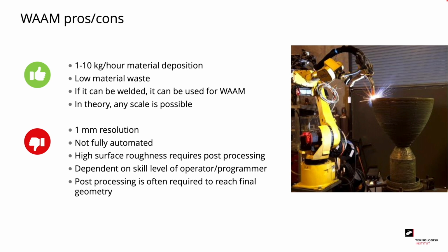Now we'll have a look at the pros and cons of the WAM process. One of the benefits is that we can deposit anywhere from 1 to 10 kilos an hour. We have low material waste, and if it can be welded, it can be used for the WAM process.